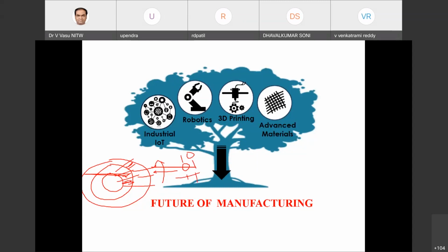Like that, if the disk coatings are like that, the starting will be 0 and 1. If the disk is rotating in this direction, it will become 1 0. If it is rotating in this direction, it will become 1 1. So if you get this position or this position, you can tell the direction in which the disk is rotating. Okay, any other questions?